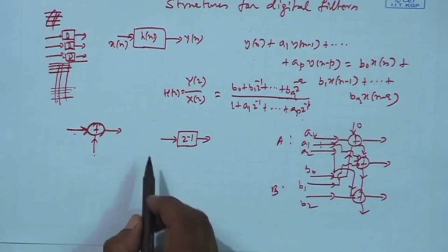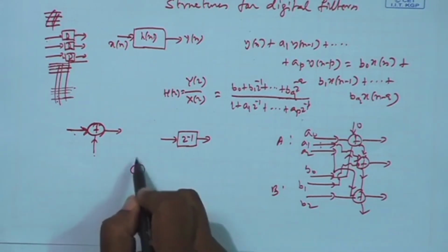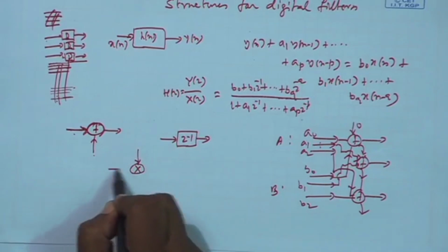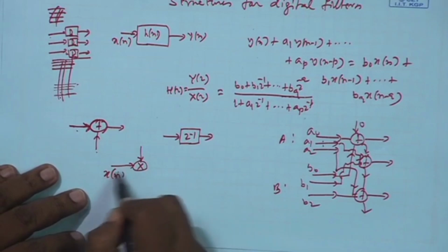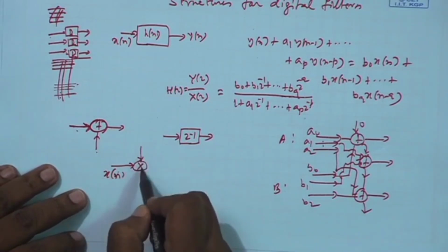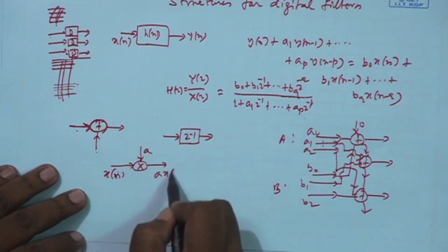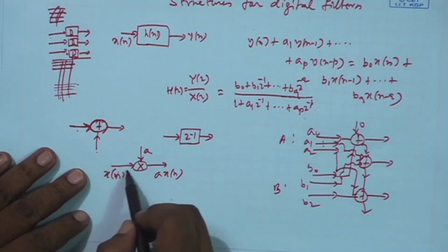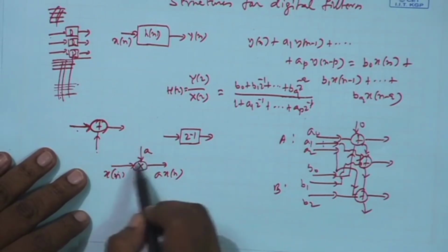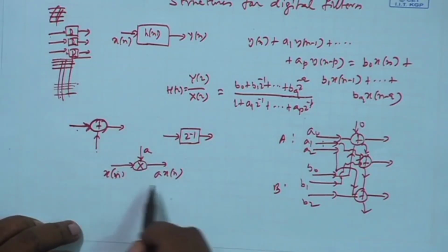And another is the multiplier. Normally these are called constant multipliers. So, there will be a signal line, there is a bus, and in this multiplier there is a built in constant, maybe say A. So, it will be A times x n. The multiplier will take all the bits of this bus and multiply that with a built in constant. This A is not a signal, it is built in. With that, it multiplies and generates the result. The result also is a bus.